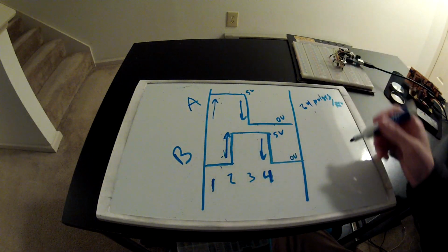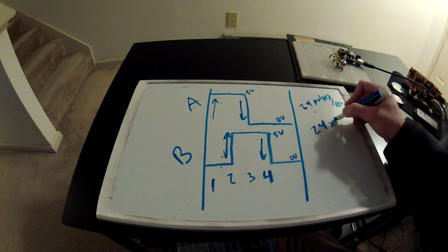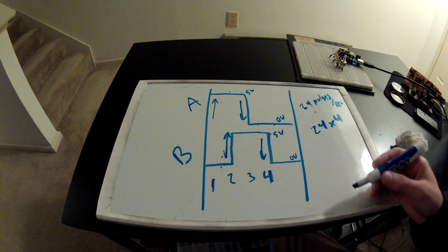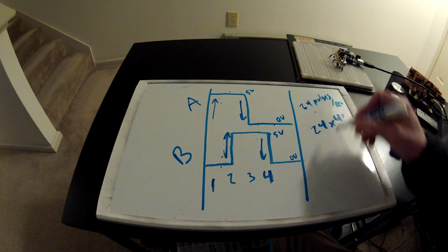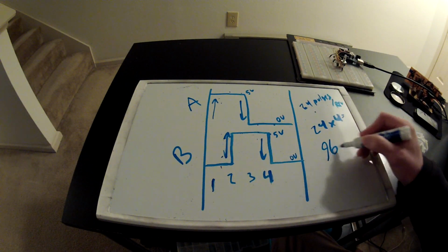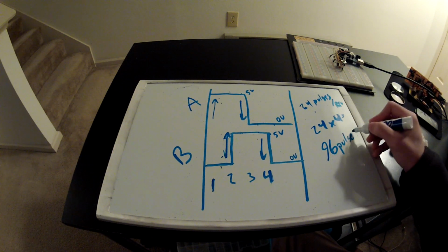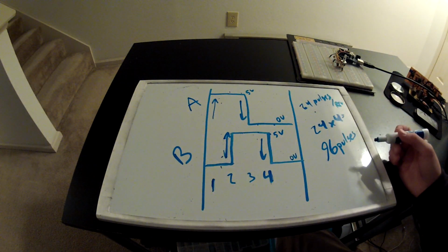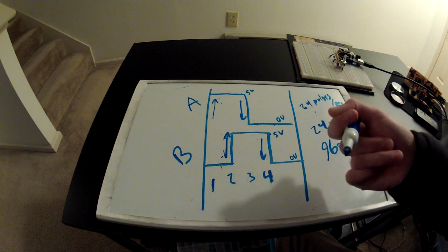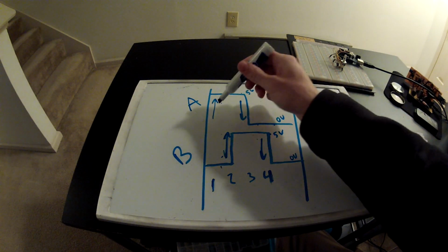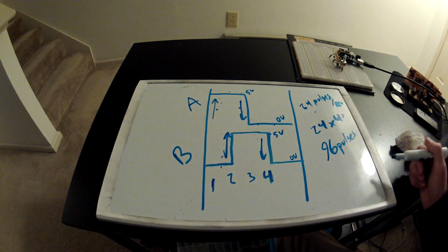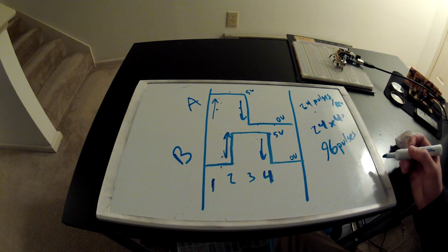So what you actually get is 24 times 4 events, basically. We're going to call them whatever you want to call these 4 changes of state, which gives you an effective resolution of 96 pulses, if you just measure pulses. And that's what we're going to measure. It's either a pulse high or pulse low. Okay, so you're going to notice that as we rotate it, we're actually going to get 96, because we're going to count each one of these events as a change in state, as a pulse, and we'll count those up. So as you move the knob full 360, you get 96 pulses.